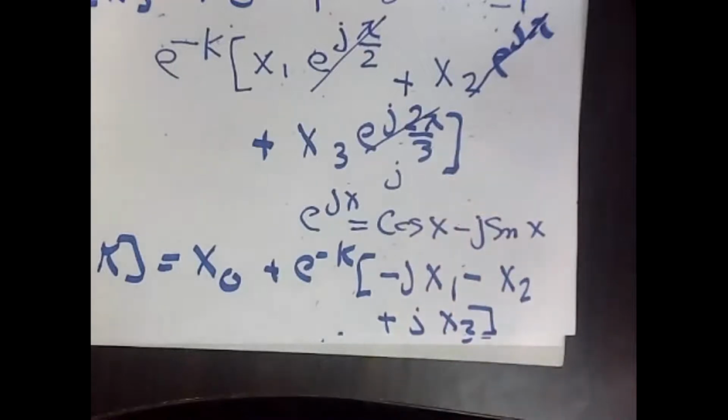If you examine now this equation, you will find that you have two types of these x of k terms. You have a pure real and you have a pure imaginary. X of 0 and x of 2 are pure real functions, but x of 1 and x of 3 are pure imaginary functions. By the way, this is not something by chance. Here, the distinguishing is basically based on even and odd functions. Even terms are real, and odd terms are imaginary. So you can classify or distinguish these terms as follows.